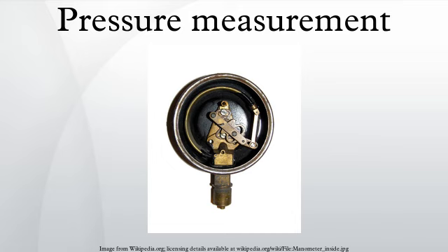Bourdon. The Bourdon pressure gauge uses the principle that a flattened tube tends to straighten or regain its circular form in cross-section when pressurized. Although this change in cross-section may be hardly noticeable, and thus involves moderate stresses within the elastic range of easily workable materials, the strain of the material of the tube is magnified by forming the tube into a C-shape or even a helix, such that the entire tube tends to straighten out or uncoil, elastically, as it is pressurized. Eugene Bourdon patented his gauge in France in 1849, and it was widely adopted because of its superior sensitivity, linearity, and accuracy.